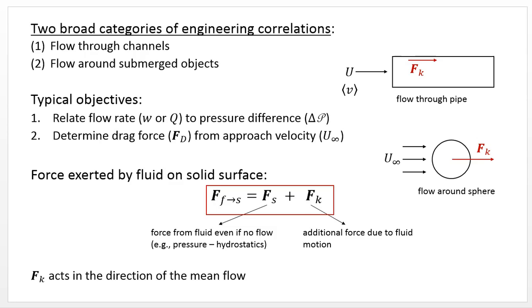Consider the use of dimensional analysis and experimental data to develop correlations, which can be used to solve flow problems, leading to approximate engineering calculations that are useful for solving many practical problems in various areas of engineering. These correlations and this type of analysis are especially useful for complicated flows and geometries, such as flow through a packed bed, which has many applications in catalysis and reaction engineering.